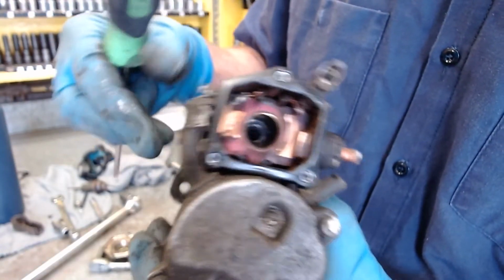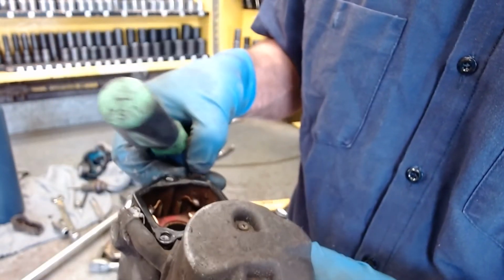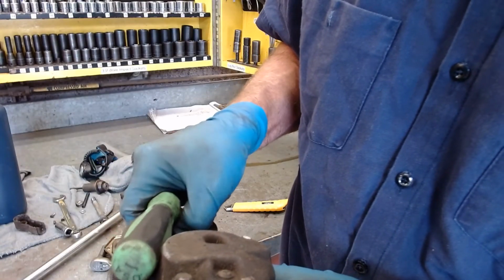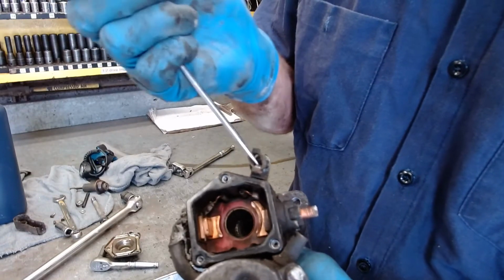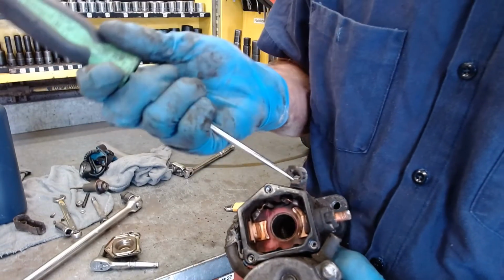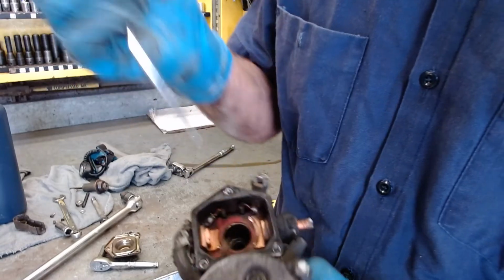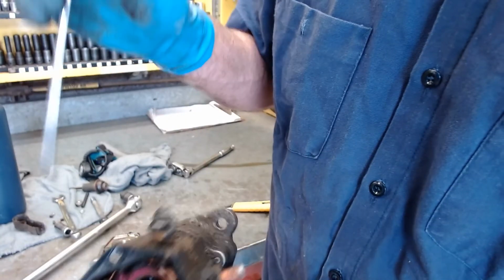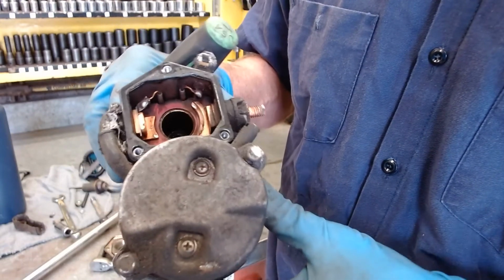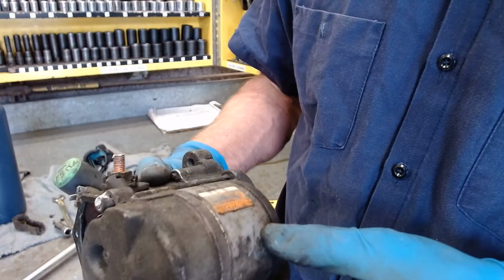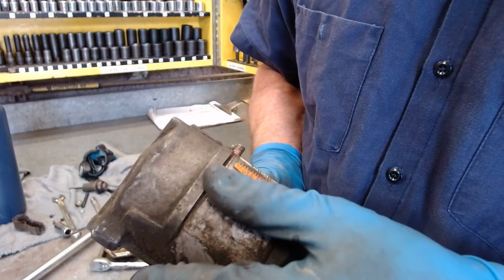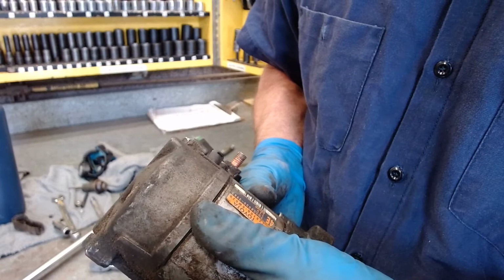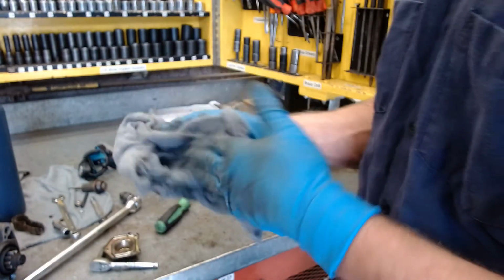But the question is, do we want to replace the starter, or do we want to see if I have another starter that I can get the cover off of this guy? Okay. So that may take care of it, just sanding those right there. Getting a new contact in here and sanding that may take care of it. But there are brushes in here under this cover that touch on the commutator, and so this is showing a Toyota factory starter motor. So it kind of makes me wonder how old it is and how long it's been in there.